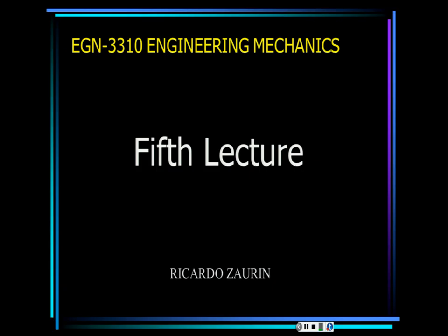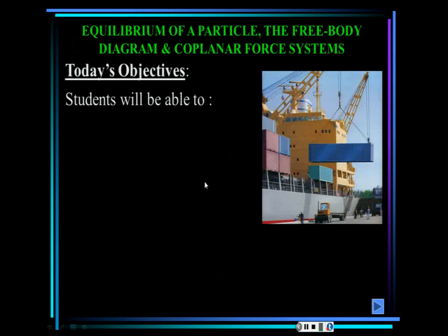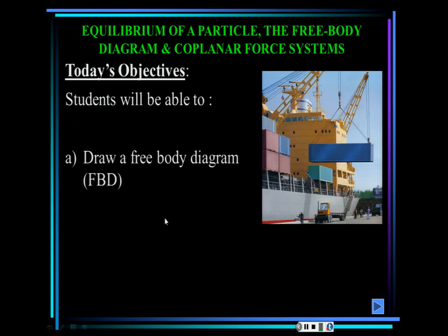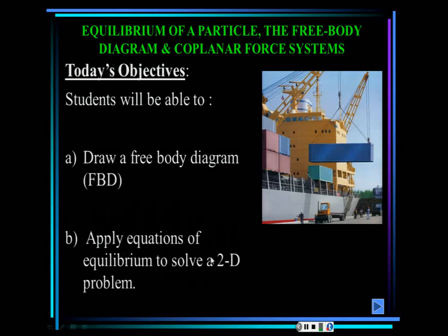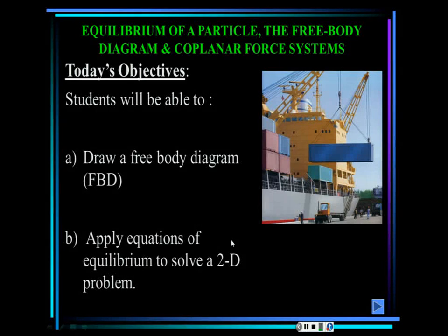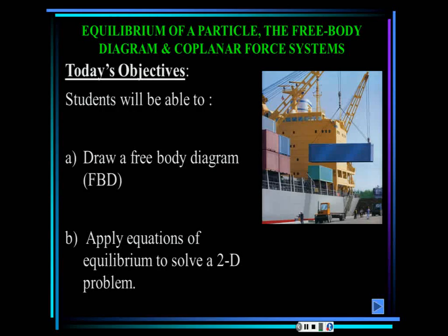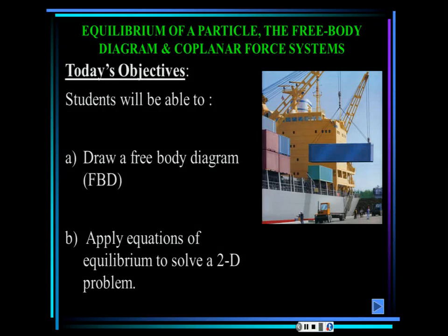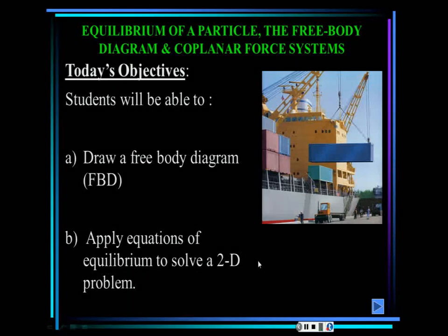We are going to be talking today about free body diagram and particle equilibrium. That's the main topic that we are going to be covering today. The objectives for today's lecture: at the end of the lecture, you should be able to draw a free body diagram and apply equation of equilibrium to solve the 2D problem. So we're going to basically be working in 2D and how to create a free body diagram in order to solve a problem in equilibrium.